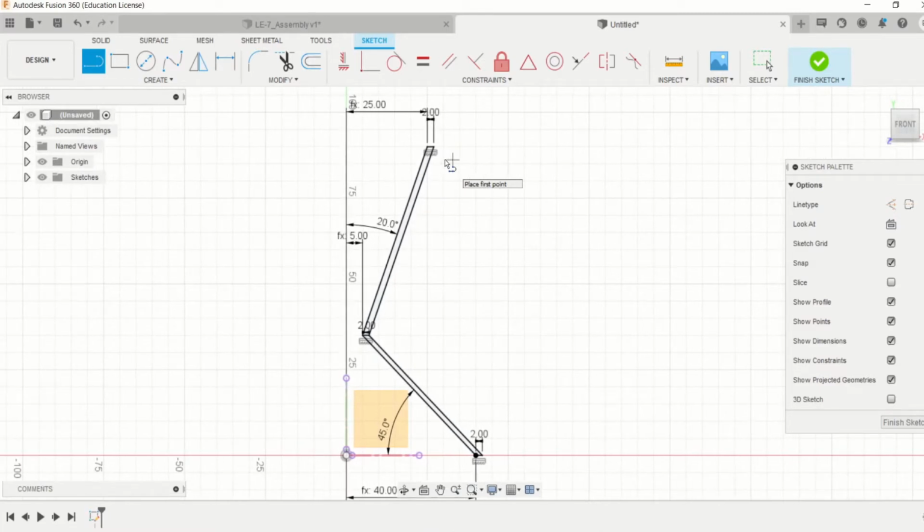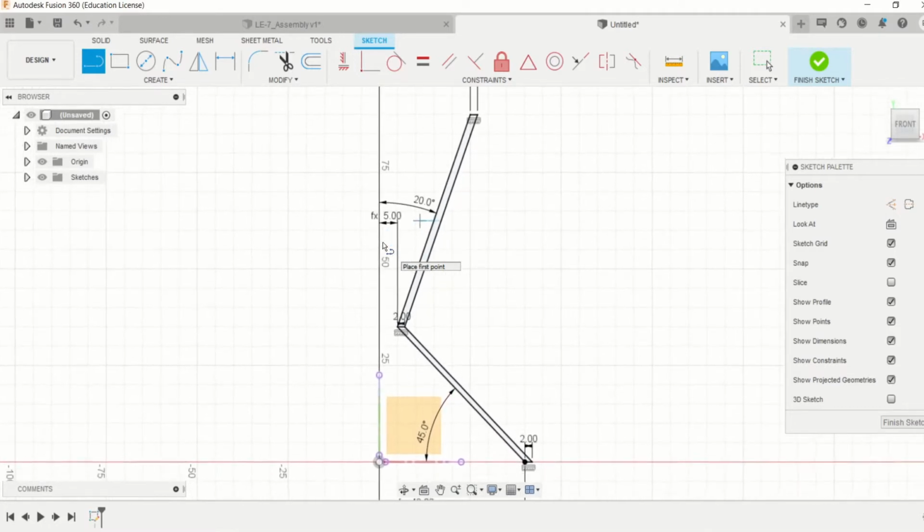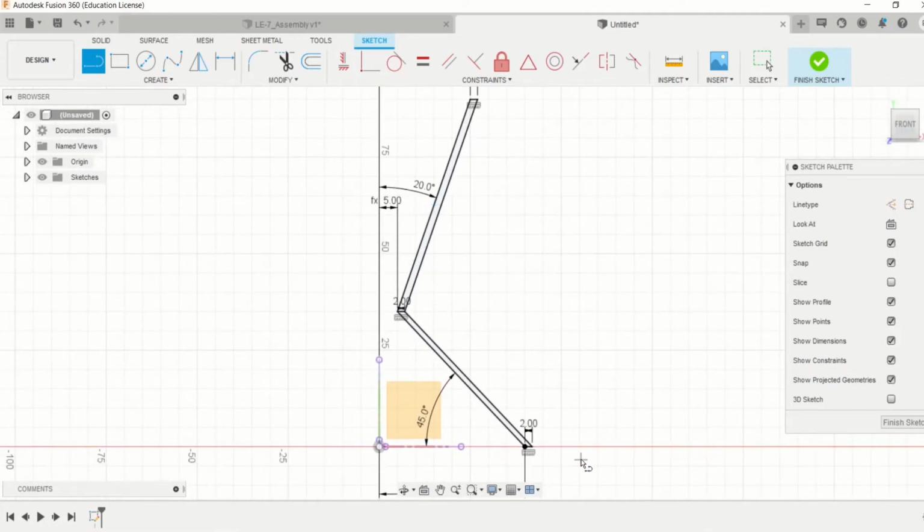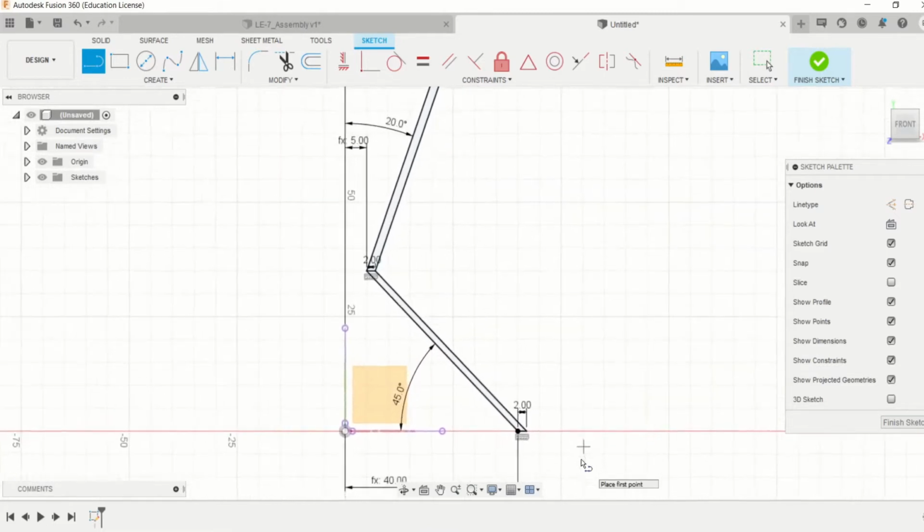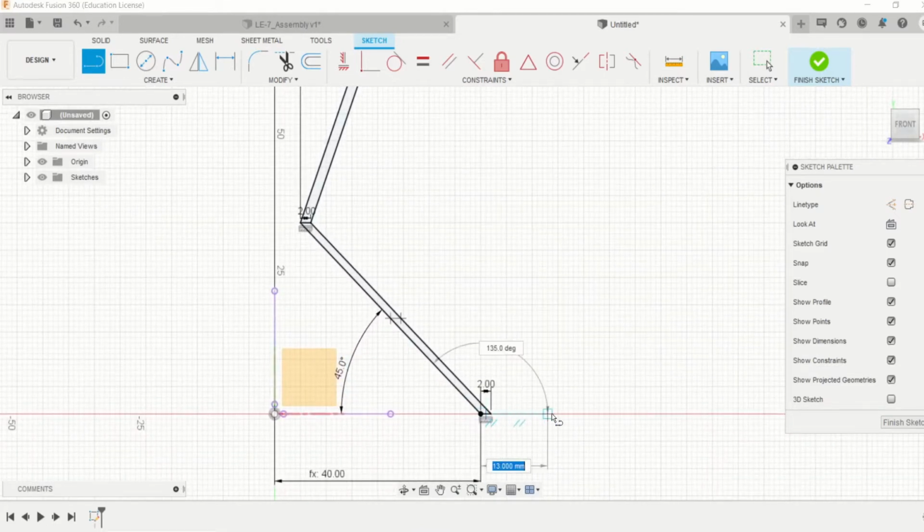Then the next thing that we will do is revolve this, create our cutouts in it, and then create the second layer, which will cover up the regenerative cooling channels. So this will be a nozzle with regenerative cooling included as well. Let's also just make a small flange of 12 millimeters, just like that.